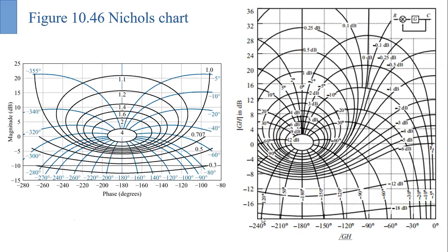In the logarithmic scale, if the gain value changes, the curve will move either up or down, because in the logarithmic scale this is just addition. A higher gain moves the curve up, and a lower gain moves the curve down. So it cannot be easily incorporated in the M and N circle.